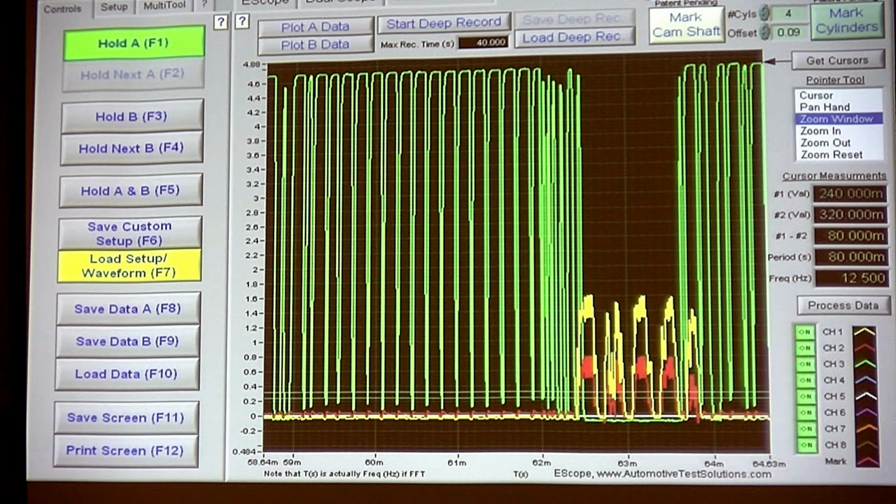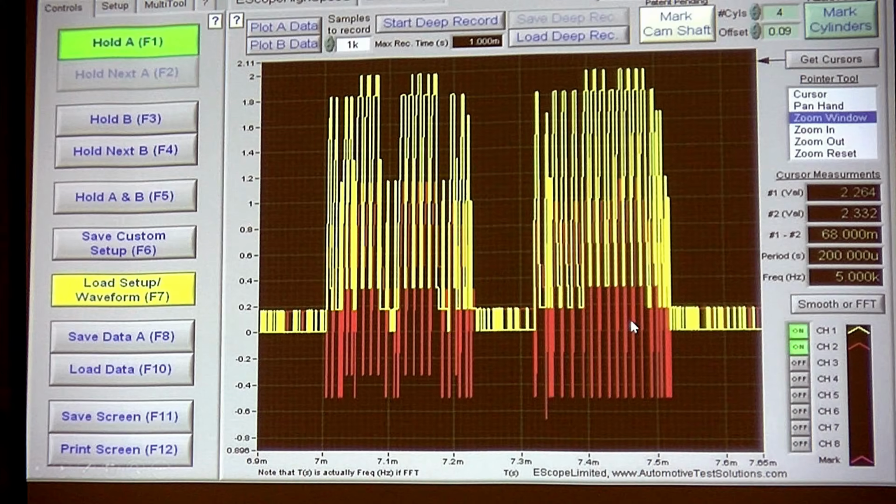Do you start to see why it's important to see who can't talk or what's not working? We just need to have a better understanding of what we're trying to fix here. This isn't going to communicate. Notice that we're pulled to ground, and both of these signals are pulled up. So this guy has got a problem. So here it is.